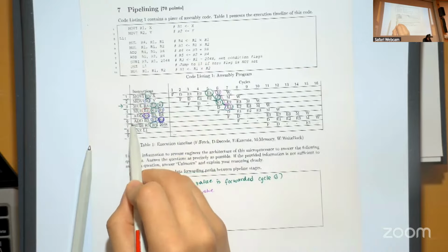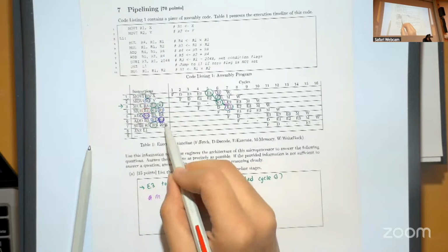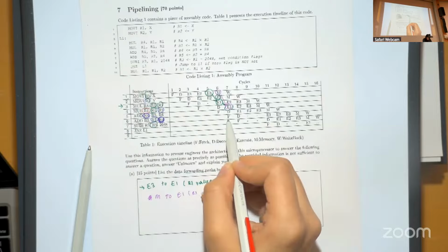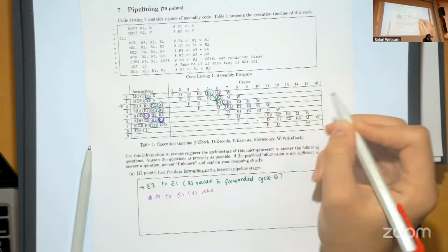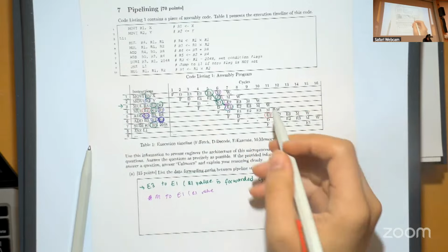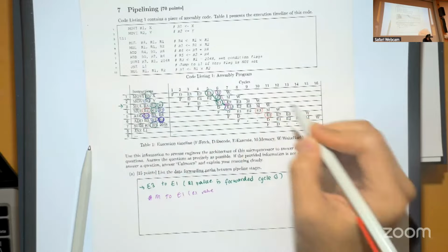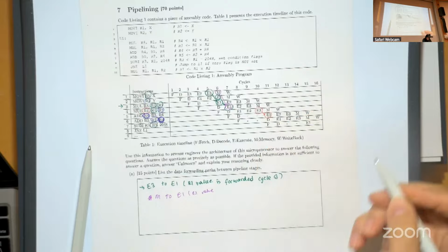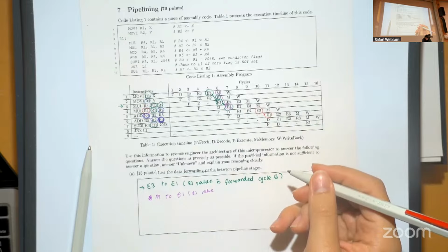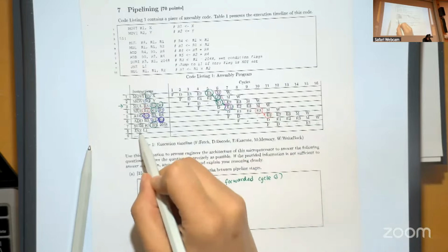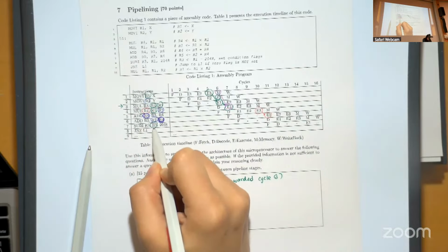And in the next one, what we see is we have a dependency for R4. And when this instruction was fetched at cycle 7, decoded next, and then waits for a couple of cycles, and after a while, it is executed in this stage. And the value of R4 was available here. So again, you can see that this is the same data forwarding path. Okay, so next, we have this instruction 7, and here R1.